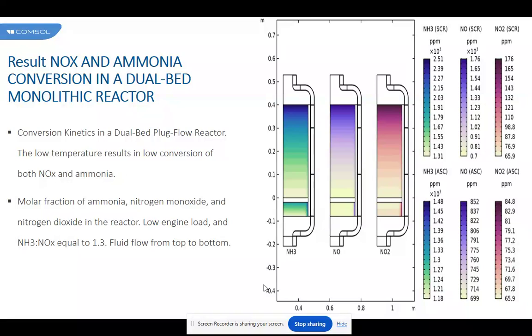The first automotive converters typically had 400 CPSI, but in the past two decades or so, there has been interest in monoliths with higher cell densities of 600 or 900 CPSI. The nominal wall thickness is traditionally reported in thousandths of an inch, with a standard value being 6.5. Improved technology has allowed thin walls of about 4.3 mil and ultra-thin walls of about 2.5 mil. Monoliths with a higher cell density typically have thinner walls.